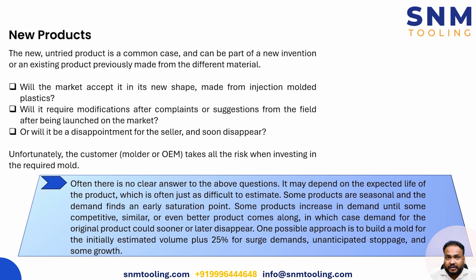Because a production mold can be a single cavity mold or a multi cavity mold. It should have better cooling channel, less cooling time. It should have advanced ejector mechanism. It should be automatic. More automation should be there, right? And the cavity should be such that the production efficiency is high, right? That is something which will reduce the cost of the product.